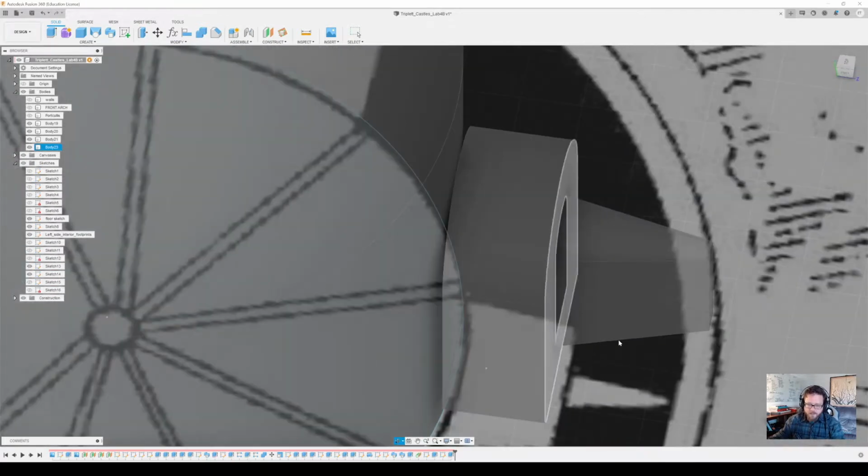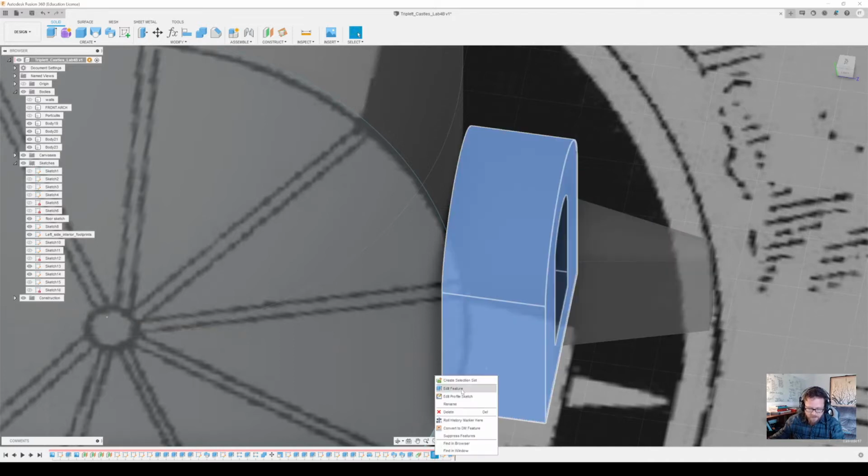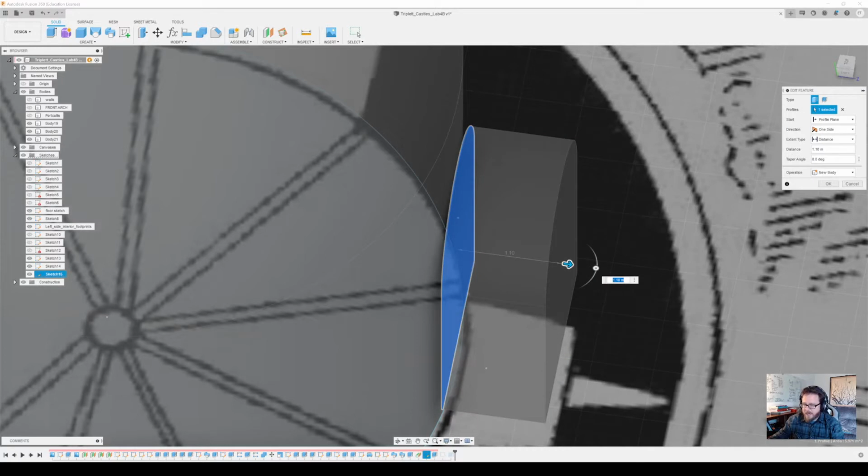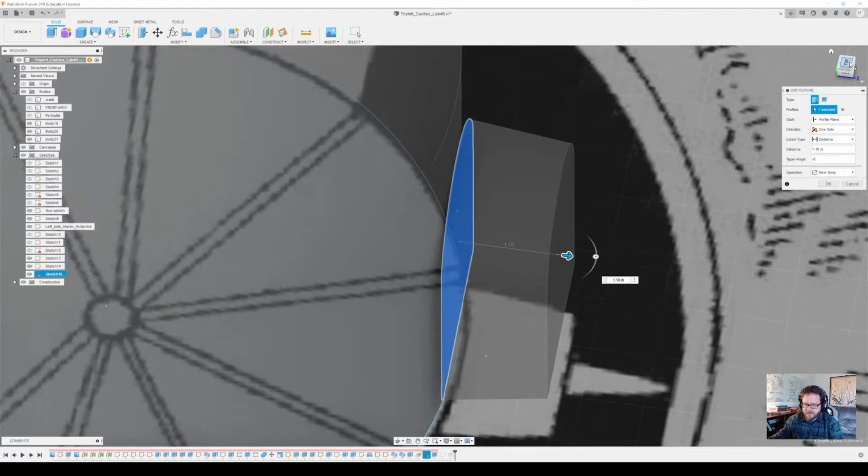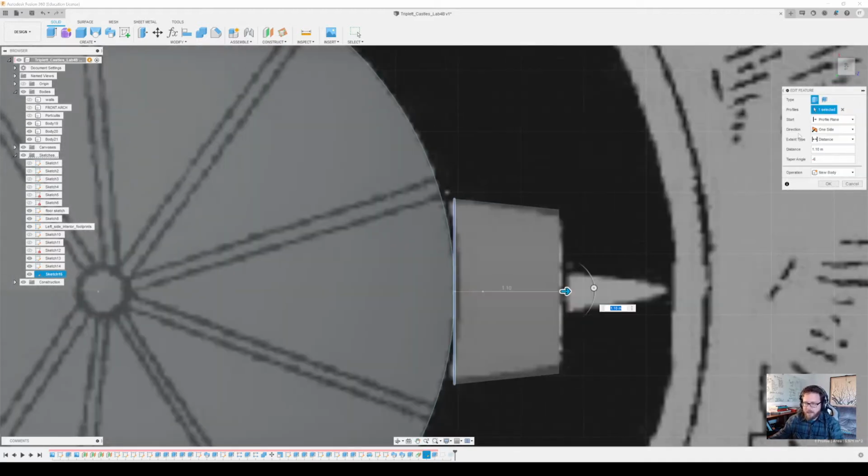What isn't tapering properly, and we may actually have to work on this a little bit. Let's go to this particular extrude. I'm going to edit that feature, and I simply forgot to taper this, let's say negative 6 degrees, maybe? Look at that from the top. Negative 6 is okay. You can even do negative 7. Yeah, why not?